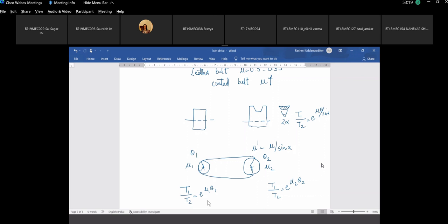Slip occurs on the smaller. Slip depends upon the friction between the two. Design consideration, failure, yes. The worst case scenario is in case of smaller theta. For smaller theta, the power transmission is less, the area is more. So we are always considering the smaller theta. This is from the safety consideration.